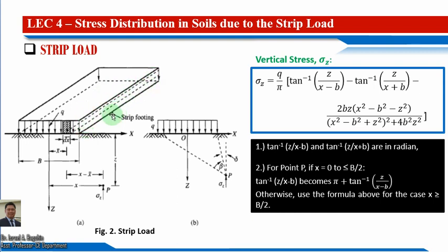For such structures, the distribution of stresses in any section will be the same as in the neighboring section, the same as that for the plane strain condition, provided that the load does not change in direction, especially if it is acting in the y direction, so that the load does not change in direction perpendicular to the plane considered. If the load changes in direction, the plane strain condition is not applicable here.